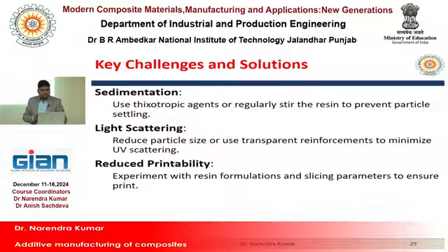Sedimentation is one of the key challenges when you go for composite development through SLA, right? Second is light scattering, right? Here we can reduce the particle size, or we can use transparent reinforcement to minimize the UV scattering.